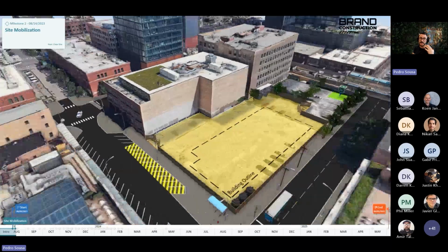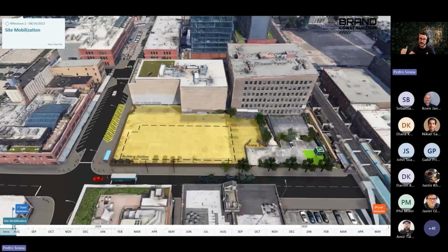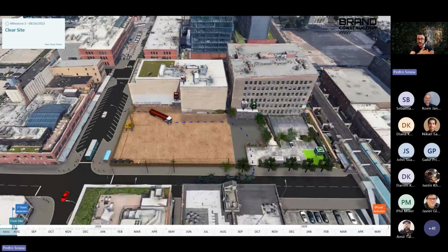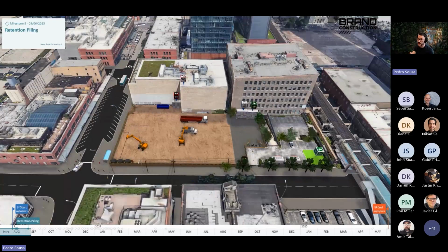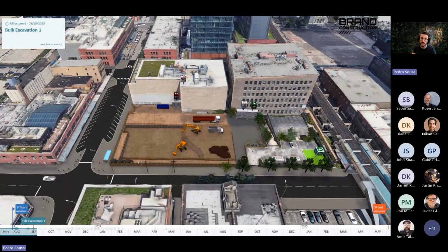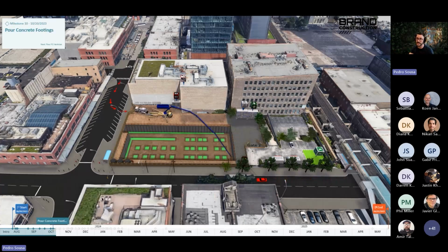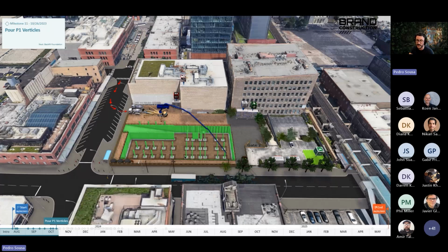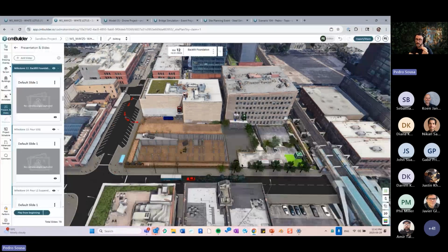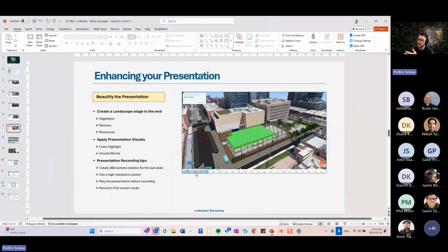So if you're about to export the video, what I suggest is play the presentation once, so it will load all of this information on your cache, like on your memory. And then once it loads and clears up a little bit of these aspects, you can go and record the simulation. Okay, so this will make the simulation that is exported as a video smoother and basically look better. Cool.